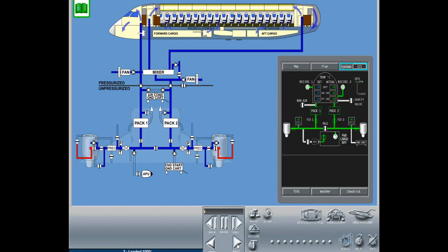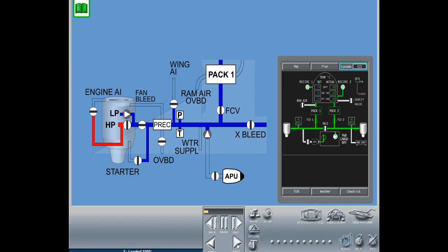The main sources of bleed air for the pneumatic system are the engines. Various power settings cause changes in pressure and temperature output, which have to be regulated. To accomplish this regulation, bleed air is taken from two different compressor stages: low-pressure port at stage number 6 and high-pressure port at stage number 10.